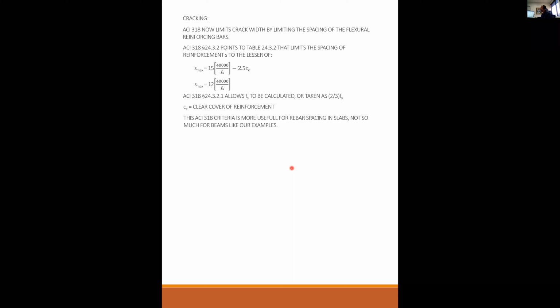But, and I wrote this on a number of your papers, I just want to make sure everybody's on the same page. You cannot take 25.59 and round it up to 26. You can't do that. Because when you do that, you're saying, I want to build a beam where the distance from the top of the beam to the center of the steel is 26 inches.